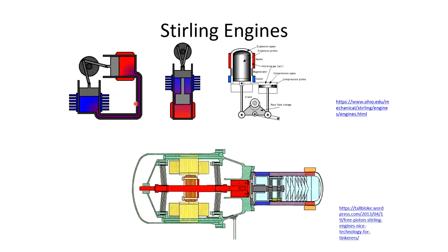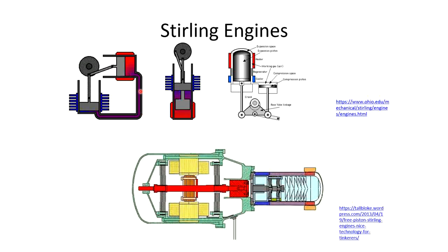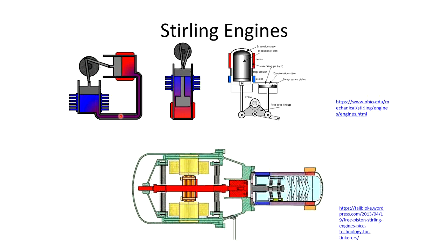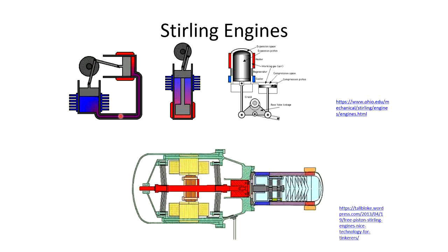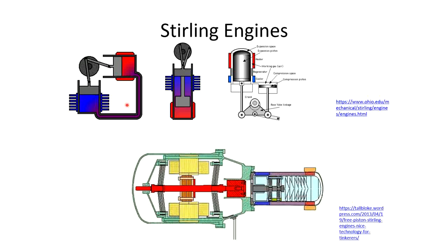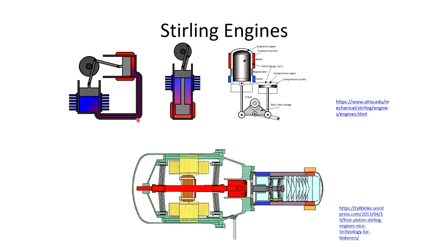The change is isochoric, and ideally in the tubing between the first and second cylinder we have some heat absorbing material which has very high heat transfer, very high heat capacity, and very low pressure drop. Now you can already hear that probably there will be some catch in how to do this in real life, but some material like this would store the heat going from the hot to the cold, and then again take the heat and heat up while going to the hot cylinder.